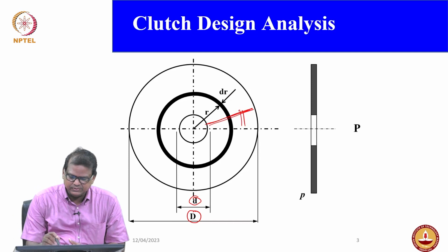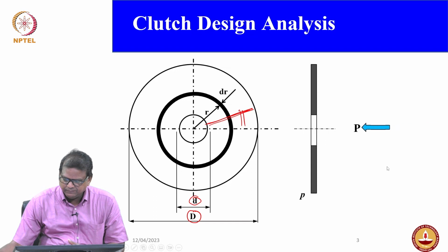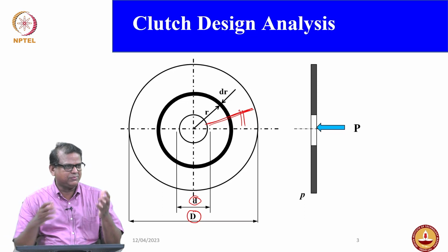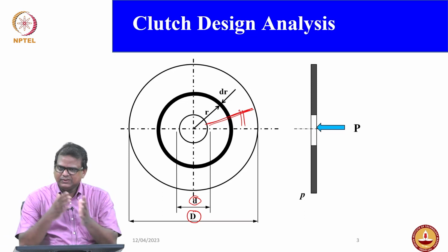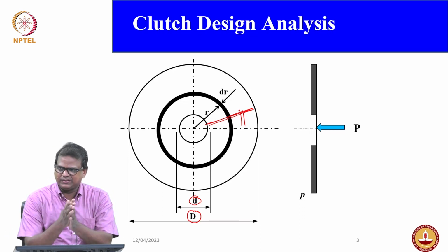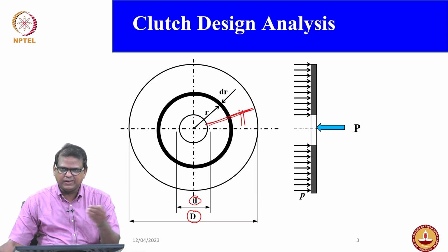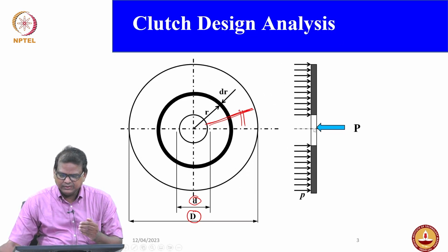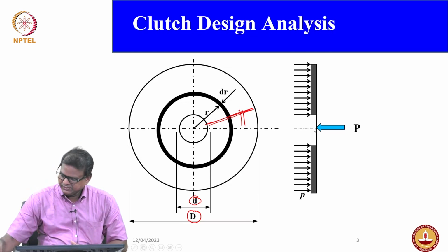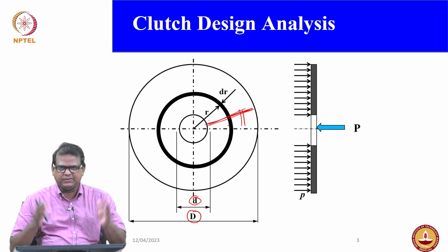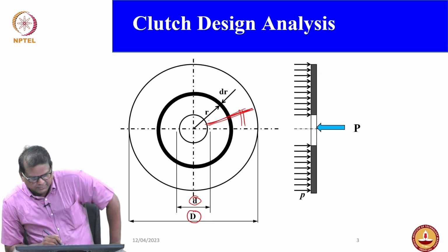And this is the side view. You would have seen the video, and I have also shown the model. You have the diaphragm, right. When you engage, it gives you a force, and the force makes the contact. So, through the pressure plate, you will have reaction forces. As a pressure along this entire area, the pressure is developed. It has to be balanced. This is the one.